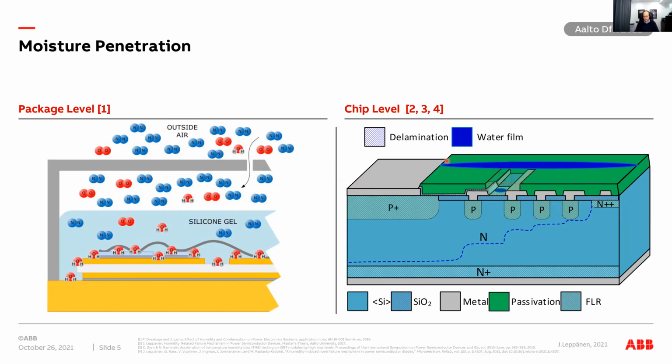This green stuff is the passivation film covering the edge termination region, and these metal plugs are the so-called guard rings that typically surround the chip. Their purpose is to terminate the electric field towards the chip edge gradually.